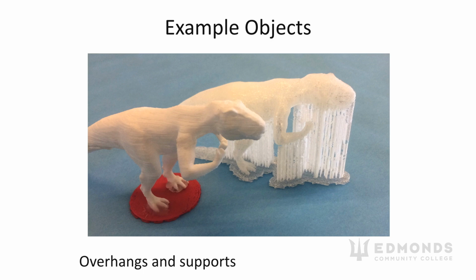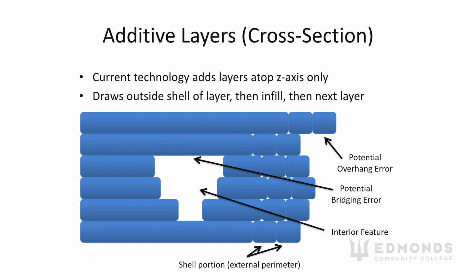So it's up to us as designers or technicians to decide which surfaces will best be cleaned of supports or how to minimize print time by putting it in an orientation where there are as few supports as possible rather than putting the supports where they will be most easily cleaned up or most easily hidden. Or it may be up to us to optimize for some other property, such as minimizing the amount of material it takes as a whole to produce this part.